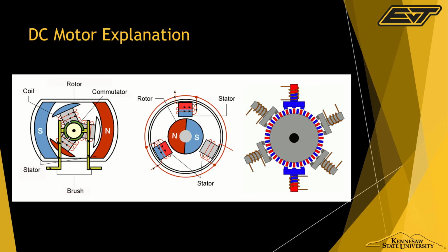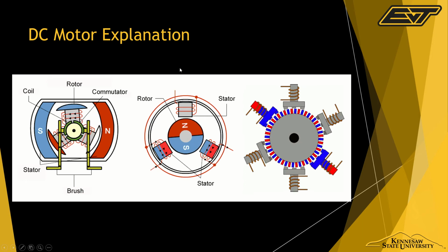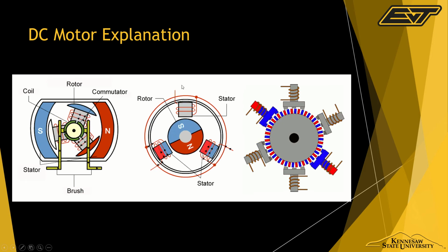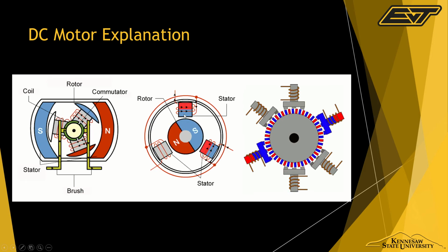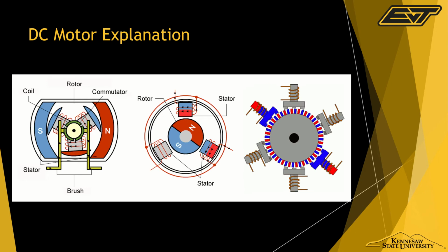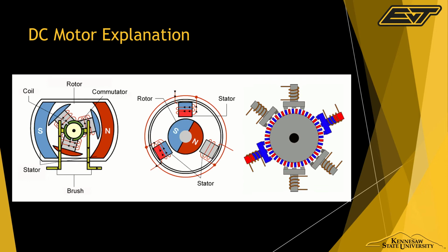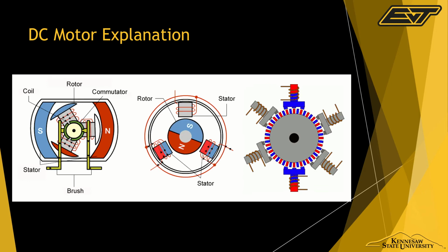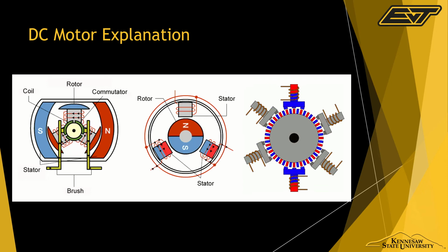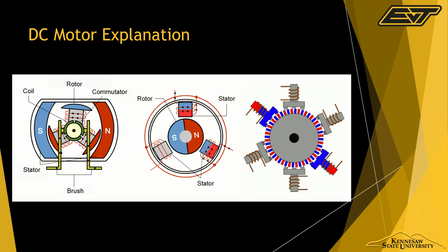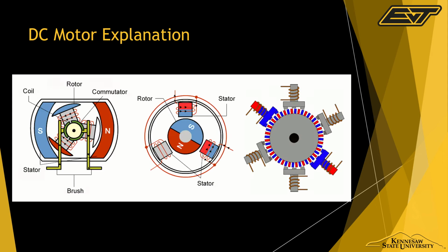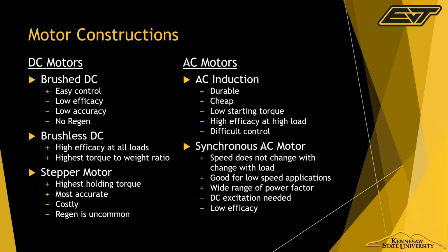the wires on the motor, instead of being powered and connected to a battery, instead they're connected to a load, and the load is recharging the battery. And basically that just causes the motor to slow down because of it. Instead of putting energy into the motor, now we're taking energy out of the motor. So before we're going from electrical to mechanical, and now we're going from mechanical to electrical. So that's the simplest way to put it. It gets a little bit more complicated than that, but we're not going to worry about that right now.